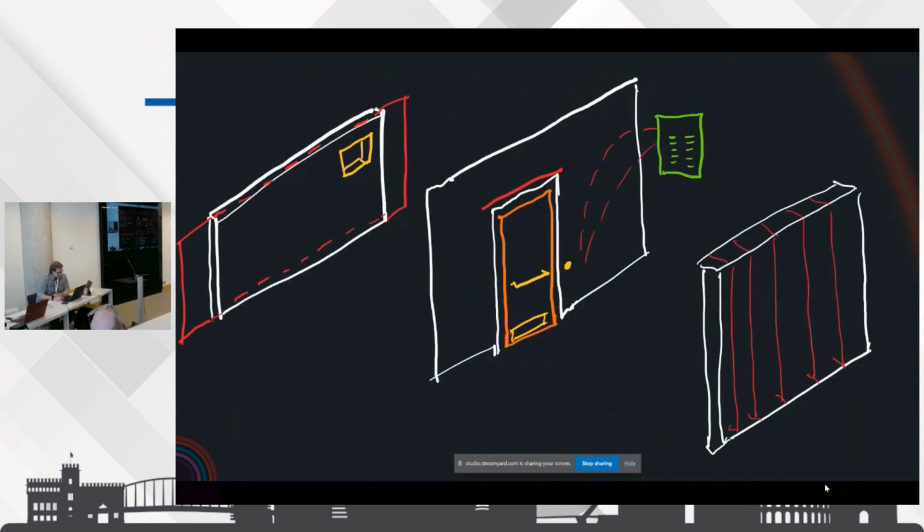IFC enables today? And a simple example is around something as simple as a wall, where a wall looks different to different groups of people. So that, from a structural engineer standpoint, they might just care about the sort of center line plus this header. The door to an architect might just look like a door, but the door to a low voltage engineer might look like the control system and the control network. These are all things that are possible to model in IFC, but they're not stuff we've decided and helped people understand how to do, again at the same time.